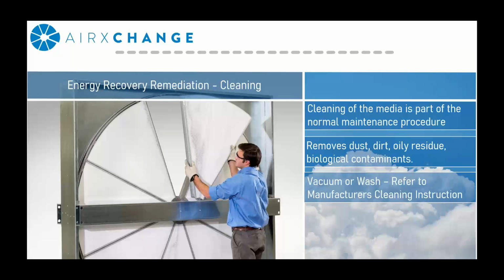So what's typical remediation for an energy recovery system? Well, it's usually cleaning. You usually do more cleaning than anything else. Anything outside of cleaning is usually more of a service-related matter, so it would be a broken belt or a motor or something to that effect.